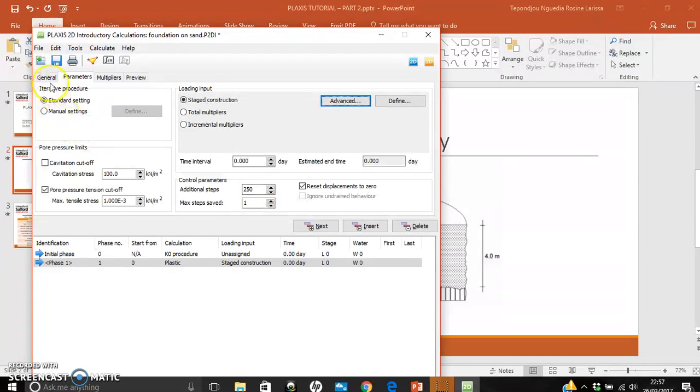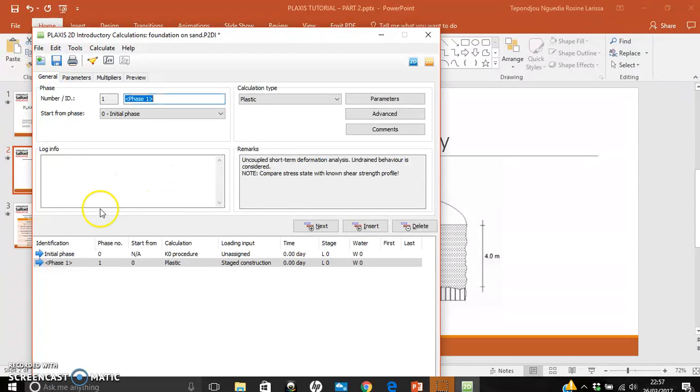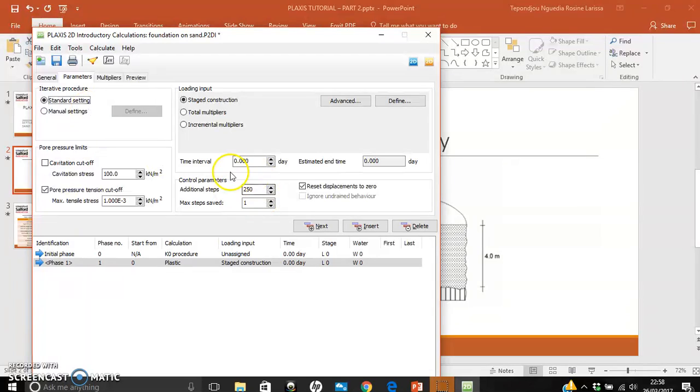When it fails, you go to the general tab, and a message will pop up telling you why the model failed, and using that reason you can fix whatever the problem is. If one of the reasons is that the maximum load step was not reached, just increase the value to give Plaxis more range to finish the calculation.